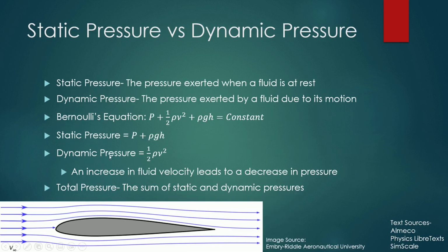And if we go back here, as we can see, we can use the dynamic pressure we get from taking the difference between the static and total pressure, multiply it by 2, divide it by the density, and then take the square root to get our velocity.